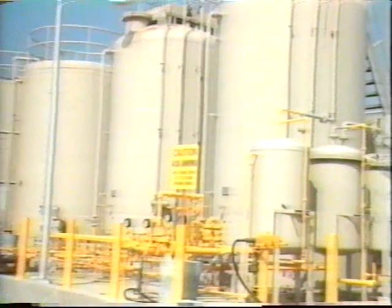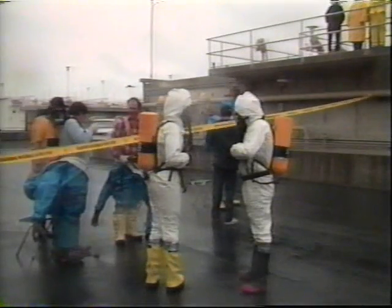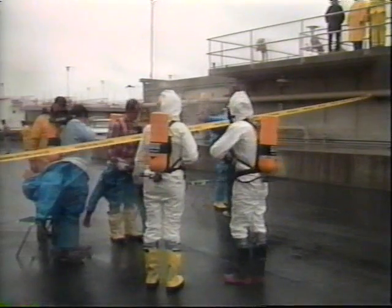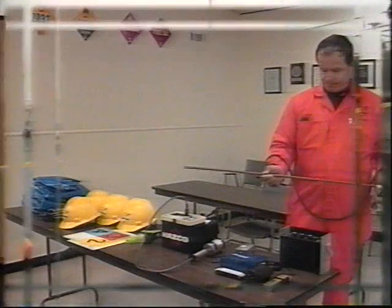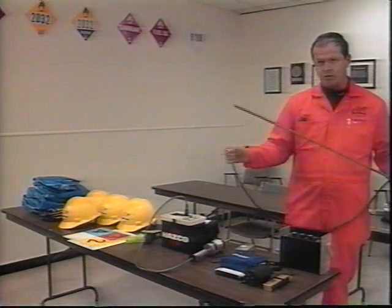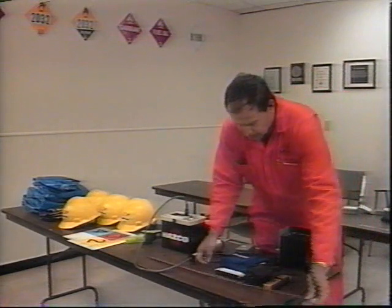Since occupational exposures are linked closely with active material handling, personal air sampling should not be necessary until site mitigation has begun. Personal monitoring samples should be collected in the breathing zone, and if workers are wearing respiratory protective equipment, outside the face piece. Personal monitoring may require the use of a variety of sampling media.